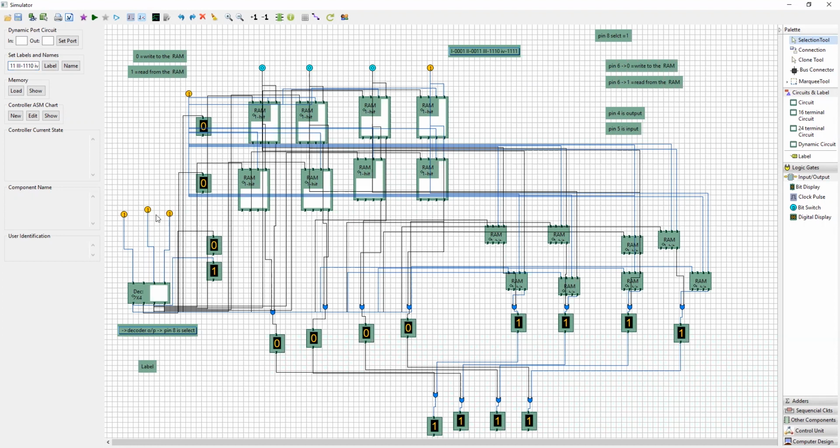First row I will go. I need to select the first row, which means I have to change the decoder to 00, and the operation I'm doing is a write operation. So 0001 I'm going to enter to the RAM cell. So I have entered it. We'll check that. We'll read it. Okay. I'll change the read/write operation to 1 now. So you can see 0001, the levels. Okay. That means these two are operated. That's why this is where you can see the output, and the final output is this. Okay. And the remaining are all deselected.